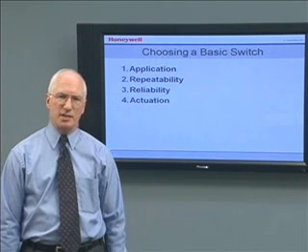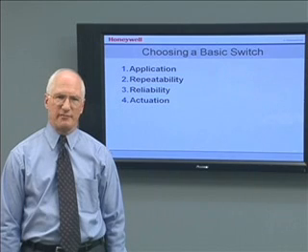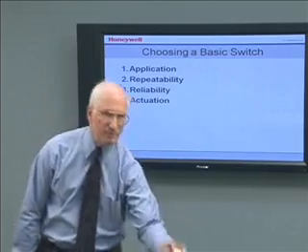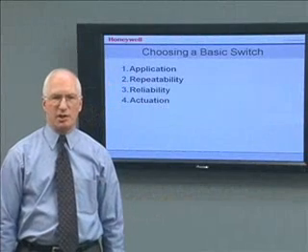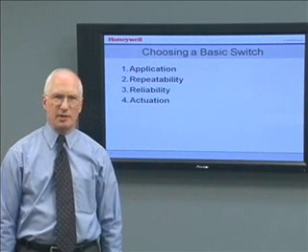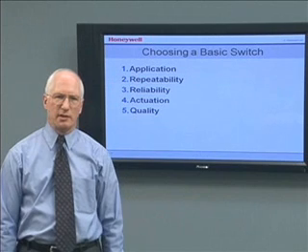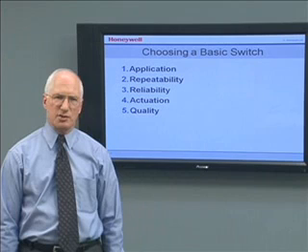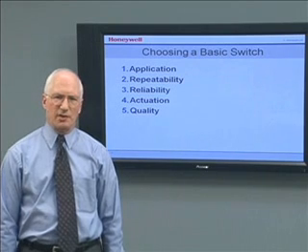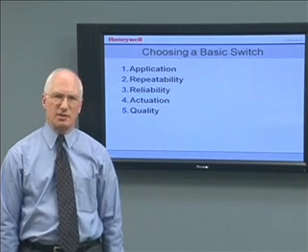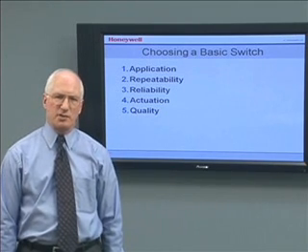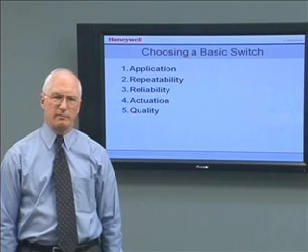Smooth actuation. A switch should be easy and smooth to actuate with a short travel. It should have a repeatable snap action feel and sound. It should not stick, bind, wobble, or change travel characteristics even after 10 million actuations. Quality. The price difference between a high-quality switch and a mediocre one is usually just a few cents. Think of the total life cycle cost, including the cost of failure, not just the cost of the component. Don't expect a commodity switch to perform like a premium one.